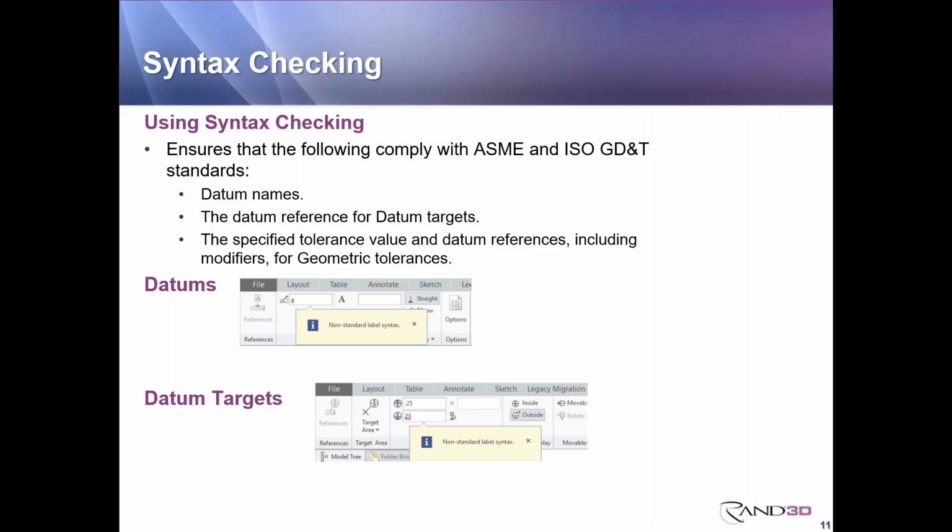So you will actually see the same red squiggly line around the area where there's a syntax issue. That's important because, as you can see from these X's in the labels or indicators, you could close those, but that doesn't negate the fact that there's a problem there. So you can see that these things let you know where to edit, where there's an issue, and also you can still create the feature with the error in it. So you can edit the feature later if necessary. That's a good thing.